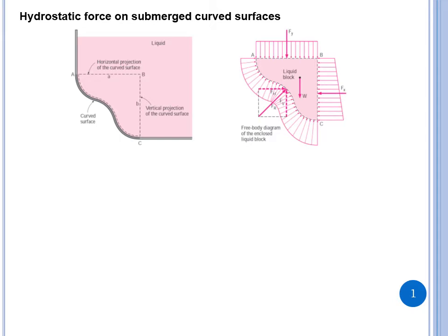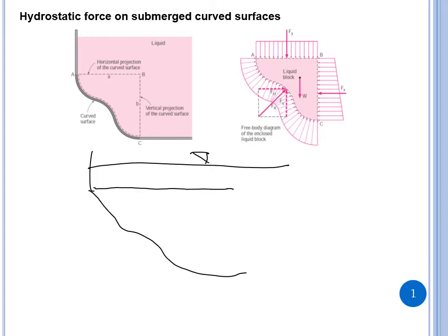So if you have any curved surface that is basically underneath the water, so you have atmospheric pressure there, what you need to do is you need to take projections. If this is x and this is y, then you take projection of the pressure or force.